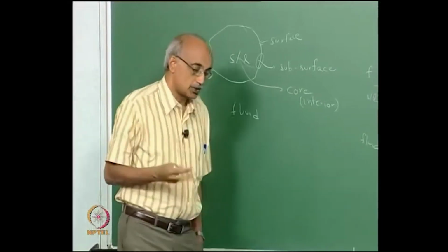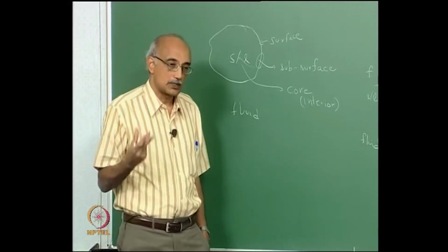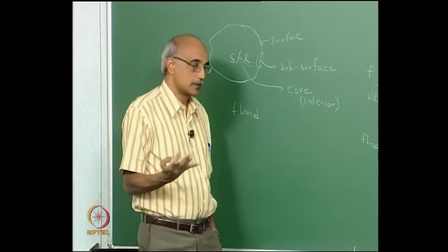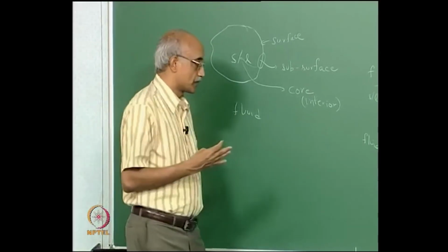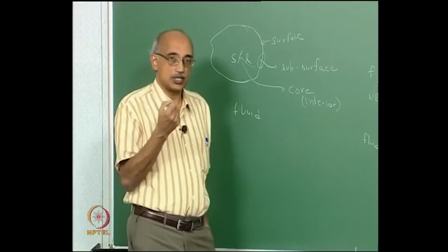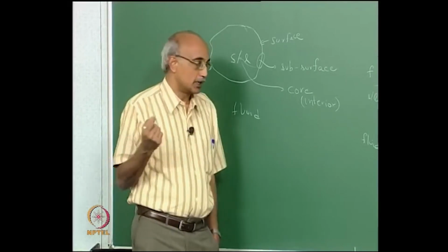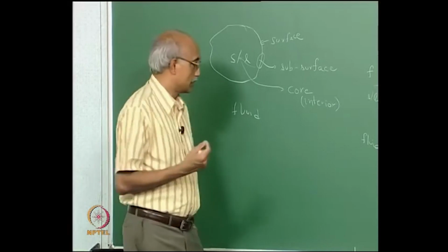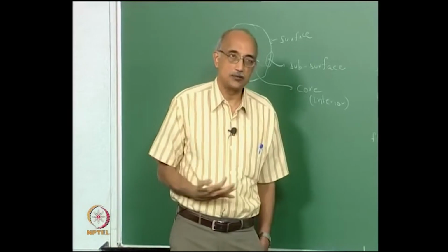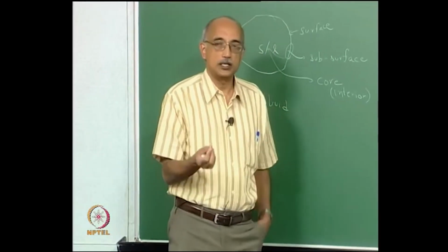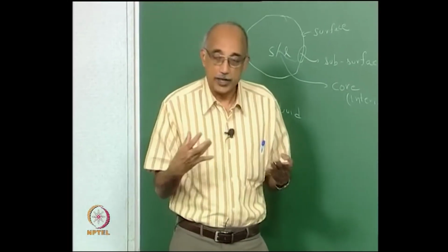The core is actually the purest representation of the material itself, because the external processes can change the properties of the surface and the subsurface, but except under exceptional circumstances they are not going to be able to change the core of the material, which will remain intact even through extremely intensive processing. So that applies once again to physical properties, chemical properties, stresses and defects and so on. The core will retain the properties of the original material that this particle is made out of.